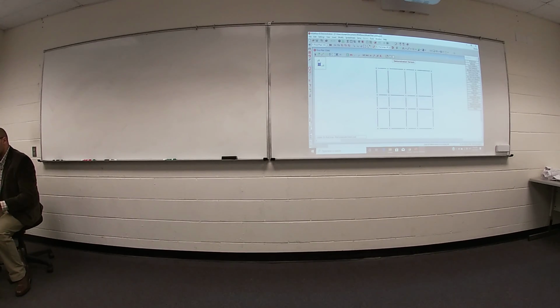Second step, I would like to draw my column. So insert, column, explicit shape, your cross section, if you have rectangular cross section or circular as you like, your depth 20, your width 20. Just click at each location of your column.